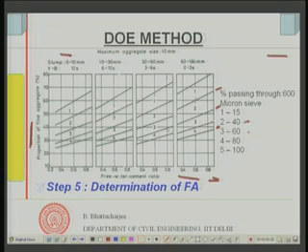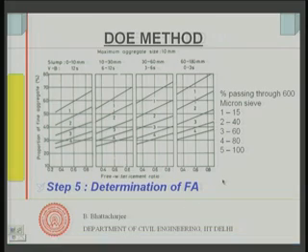let us say I have got the finest of the sand, everything passing 600 micron, and my water cement ratio is somewhere around 0.45, let us say, then my percentage of the sand in the total aggregate will be around 33%. So, I will have 33% of the sand in the total aggregate system if my MSA is 10 millimeter. So, this is how I determine the sand content in total aggregate system.